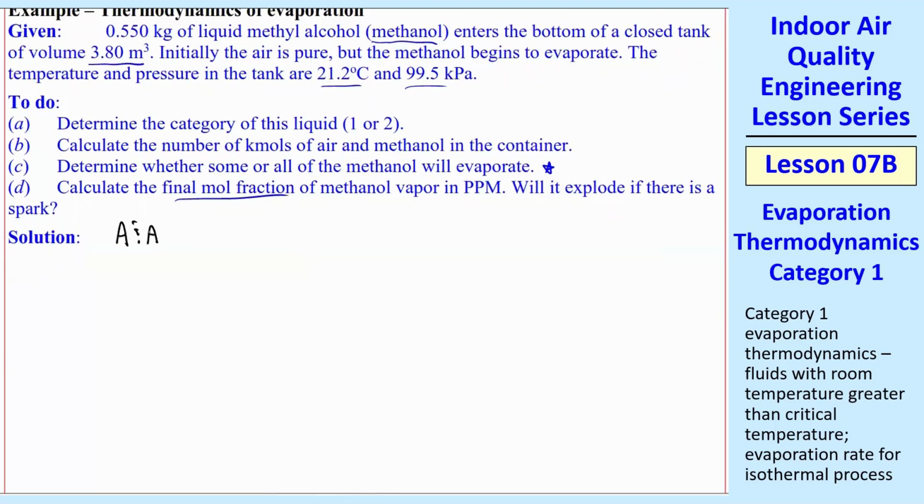First of all, assumptions and approximations, and you'll always make this approximation unless I tell you otherwise. We'll assume that V of the liquid is much, much less than V of the air. So we're talking about a case where we have some container and the liquid is just a small fraction of the volume. So we'll let V equal constant at all times. We'll ignore any displacement effect. In real life, as this liquid is removed, it's evaporated. The volume in the tank, the gas volume, becomes larger, but we're going to assume that volume is constant. Otherwise, this gets much more complicated.